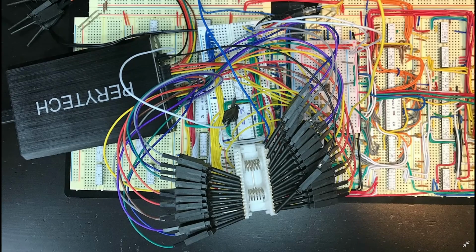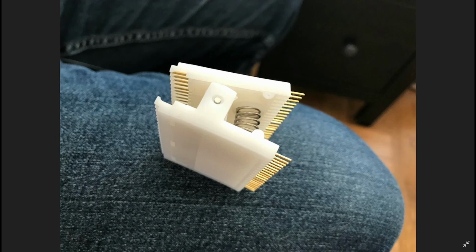So as you can see here, this circuit looks a bit of a mess now because we've got all of these probes on the CPU. It's a bit tricky to do this, but it's made a lot easier by using a special clip. This clip here is something you can clip onto the CPU. On the left side there, that clips over the legs of the CPU, and on the right hand side you can put your logic analyzer probes on the top, and it just gives a lot more space, and they're a little bit smaller than the legs of a CPU or any chip, to allow you to put a lot of probes on to a small space.